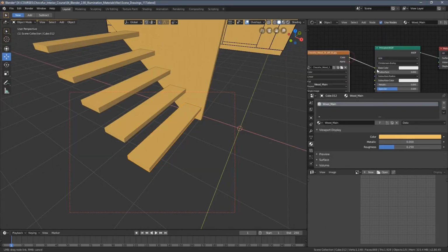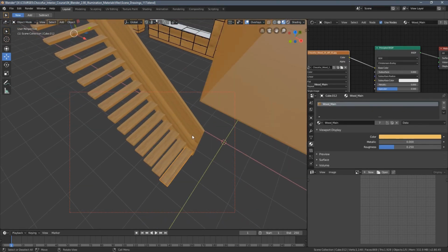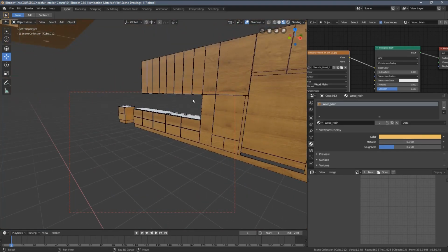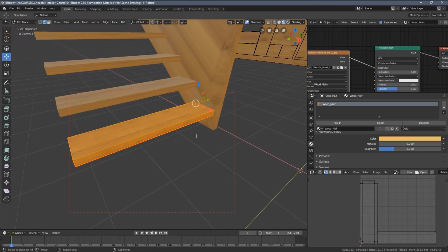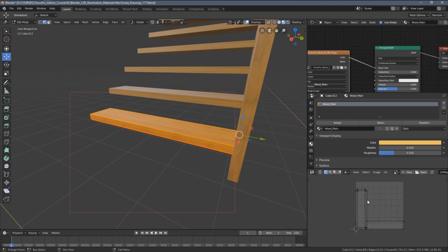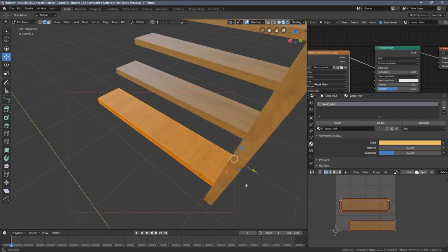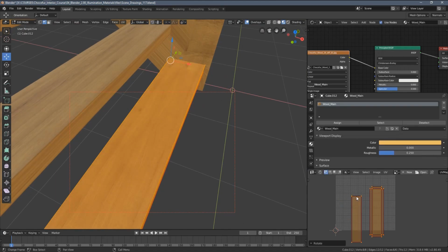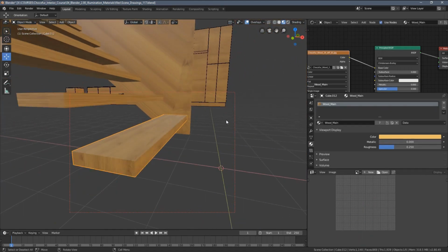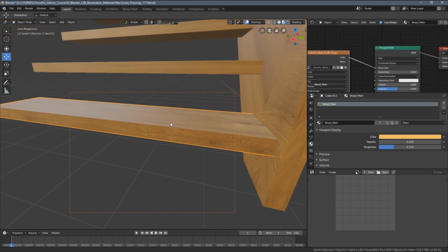So let's plug it in here and switch to the look dev view. You can see the texture already displays on the model in a very generic way, but let's ignore that and simply focus on our model. You can also see in the UV layout that we have those 2 islands rotated. So let's make them horizontal, but it doesn't look good in the viewport, as you can see. So let's now rotate them all together. And this gives us pretty nice looking mapping on the object.